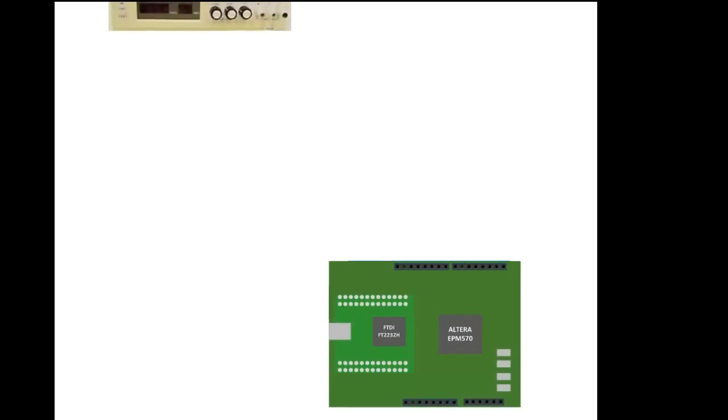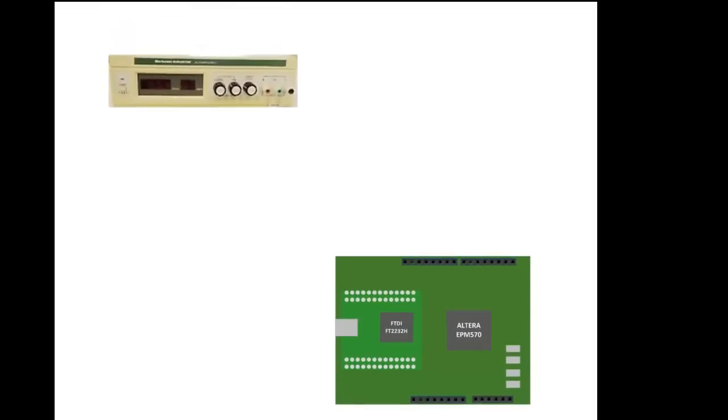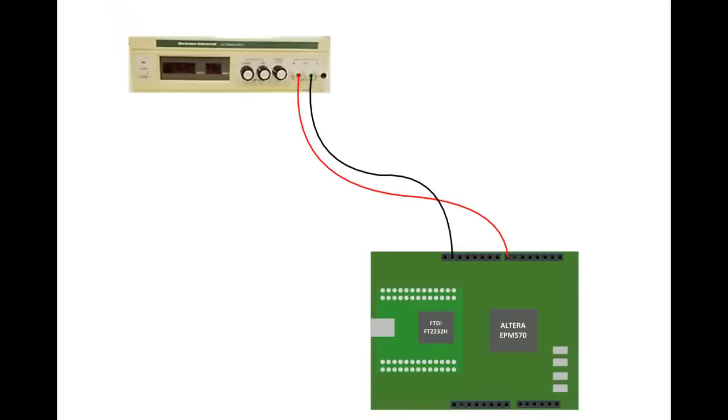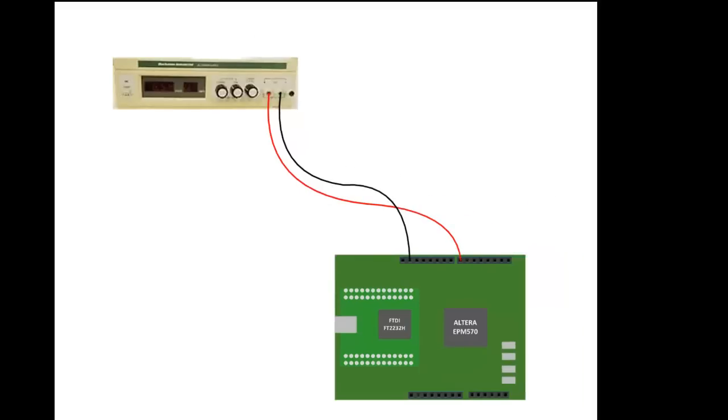To do this, connect the Uno Pro Logic to the Uno. Next, connect up the positive 5 volt variable power supply. Connect the ground pin to pin 6 of J12 of the Uno Pro Logic. Connect the positive lead of the power supply to digital input 7, pin 8 of J8. Next, connect the ground lead of the function generator to pin 7 of J12.